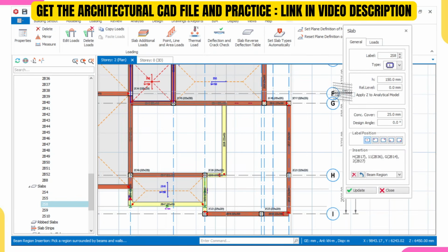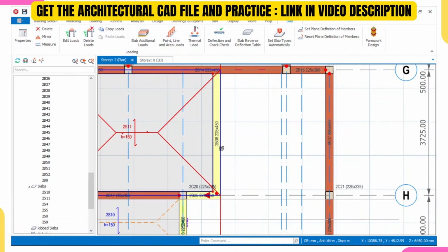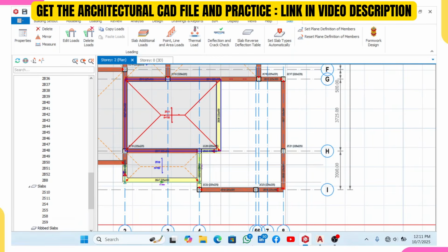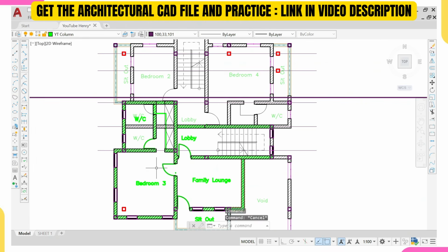Then I'll double click on this again. Once I double click on it, the beam property will appear. Then I'll place a slab here. But if you check, there will be no wall load here. This will not carry any wall load. Let's go and check so you see. Yeah, we are having this here, so let me just delete this. So I'll do E, enter.